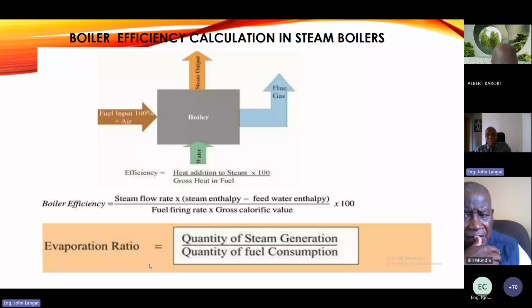Normally, when you're auditing, especially the boiler, personally, I've seen some energy auditors spend only maybe 1 hour or 2 hours auditing a boiler. You might have to take something like 5 hours to 6 hours just so that you can pick out all these parameters, because you need to check. And the best time to go is during maintenance day. When you're doing your walkabout, you need to ask, when is your maintenance day, when they are not processing, when they've opened the boiler for the weekly maintenance.